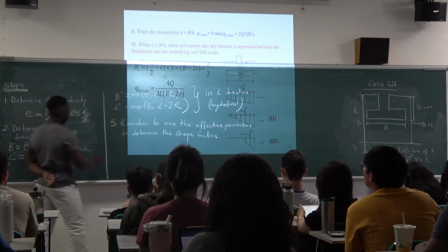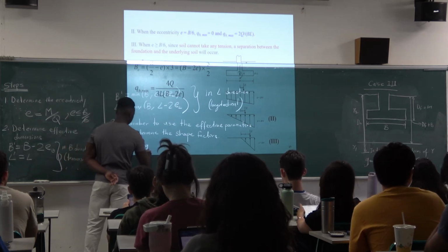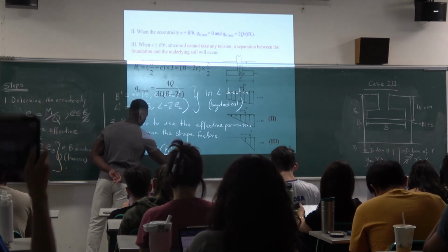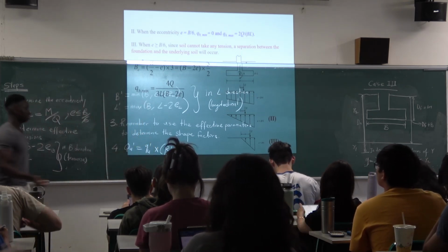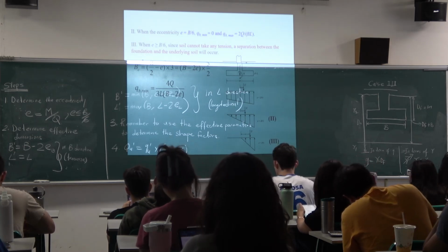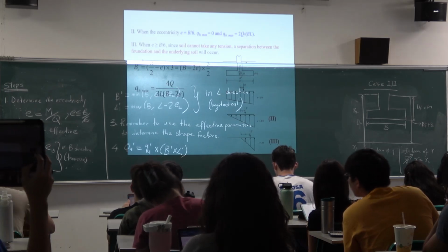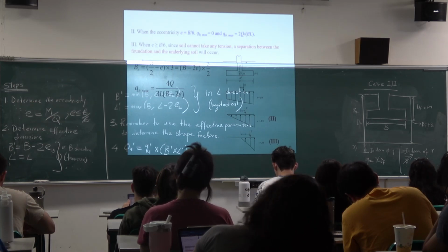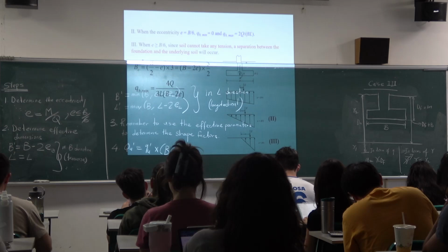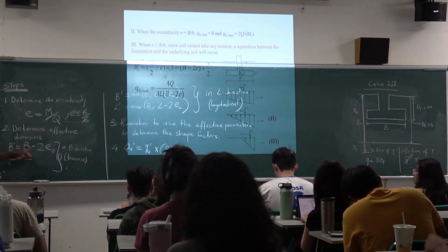And the final step: if it asks us to find the loading, q_u, it's also going to be the same. You have to use the effective dimensions. Just like in the previous part, when we talked about the foundation pressure, we paid more attention to q, the stress, and gamma. In this type of problem, we have to pay more attention to the effective shape parameters.